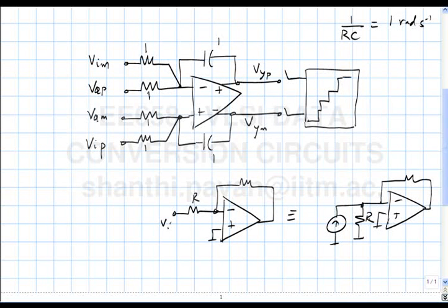So if you look at the resistor there in the Norton equivalent, what is the voltage across the resistor? 0, because one end is real ground, the other end is virtual ground, so no current flows through it, so I don't need to have it in the first place.